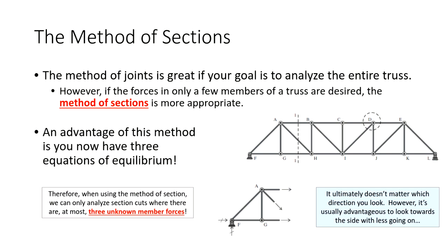And you can handle that one of two ways. Start doing method of joints analysis, which is fine. There's nothing wrong with that, but it can take a while because, if you're trying to do member IJ, you might say, okay, I'll start at joint L, and then I'll go to joint K, and then maybe joint E, and then joint J. So you're having to do quite a bit of work just to get to IJ. Whereas if you just cut a section in some moments, at a particular point, you could be done with it. So it's a very valuable toolkit for the FE exam.